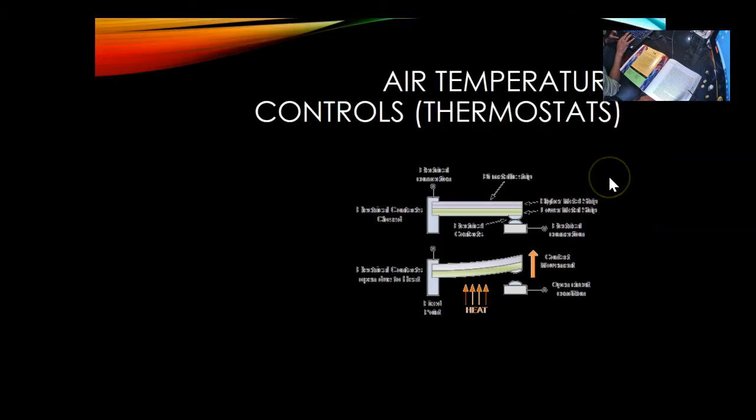This is something you would have seen a lot now in chapter 12, and I just went through it, which is the snap action or the bimetal thermostat. Again, this is very, very old technology, but it's still being used, where you have a bimetal that expands and contracts, and it provides this. There's a magnet here that can attract that piece of metal to provide that snap action.